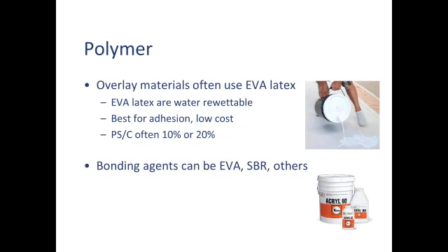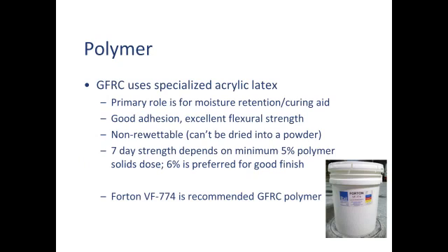In the decorative concrete world, the most common ones are used for overlays, whether it's skim coats or stampable overlays or things like that. These are glues. They're bonding agents. They can be added to the mix, but they're mainly rolled on or brushed on or troweled on to act as a bonding agent, a glue, in other words. Sometimes they're also blended into the mix to give it a better flexural property so that the thin overlay doesn't crack as much. And they tend to have high solids contents.